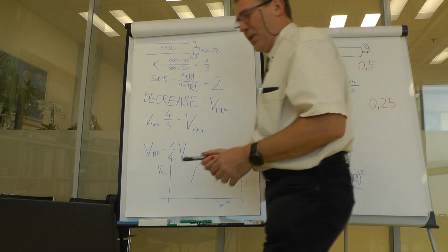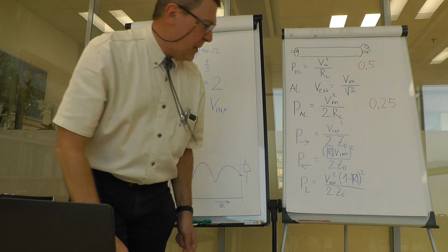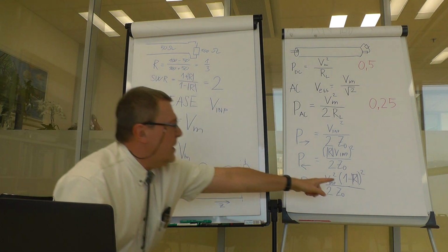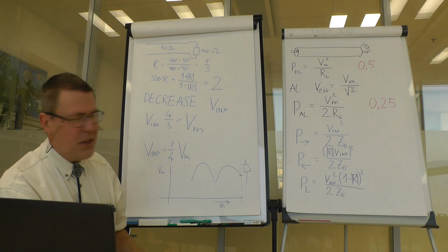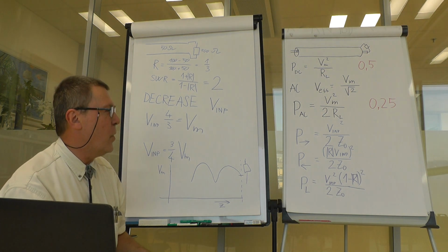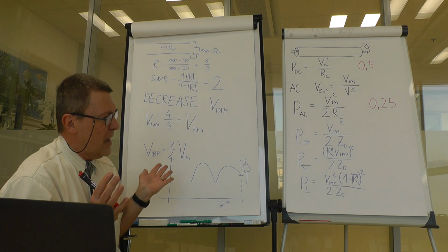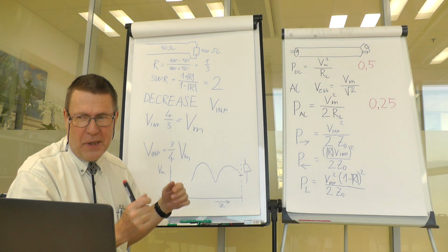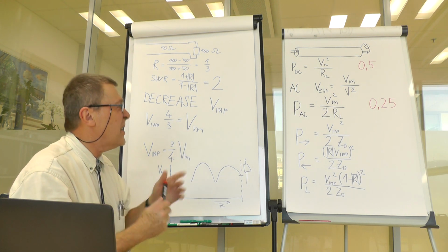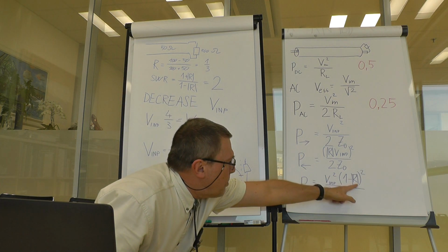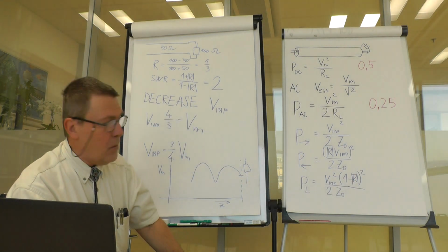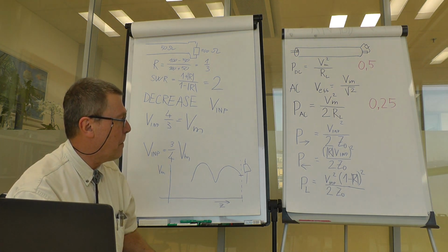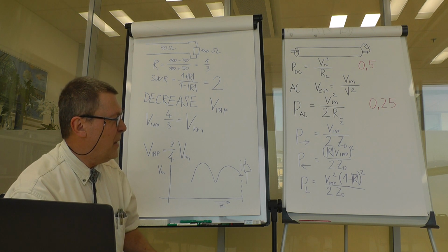And now we will have to get a calculator and do some calculations here. So first we have the reflection coefficient, which is 1/3. Now this is quite a small reflection, as you can see. A standing wave ratio of 2 seems to be a lot, but it could be even worse. So this bracket turns into 1 minus 1/3, which is 2/3, and 2/3